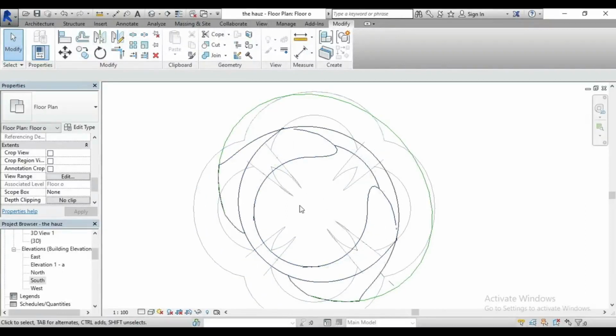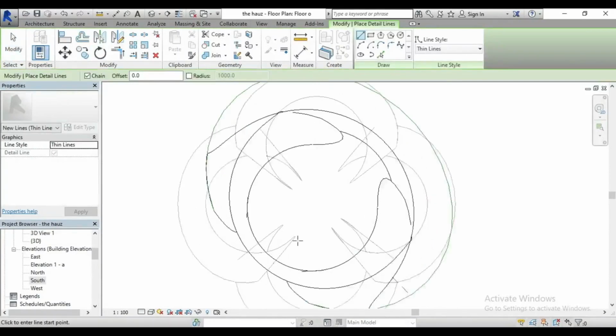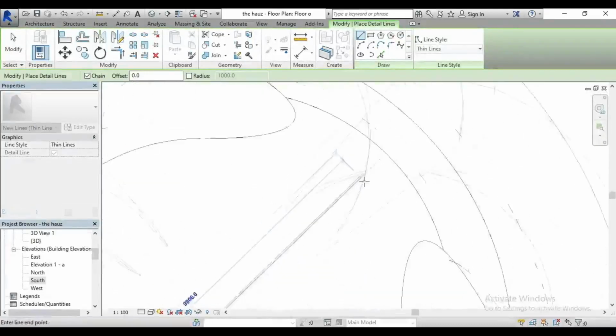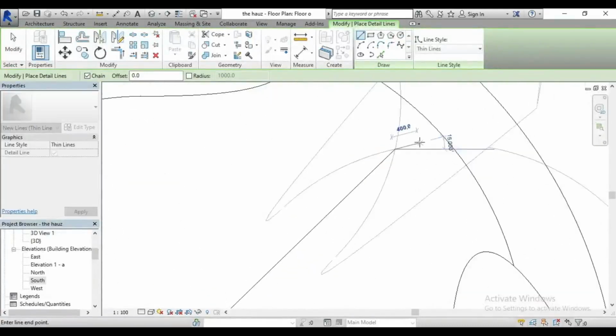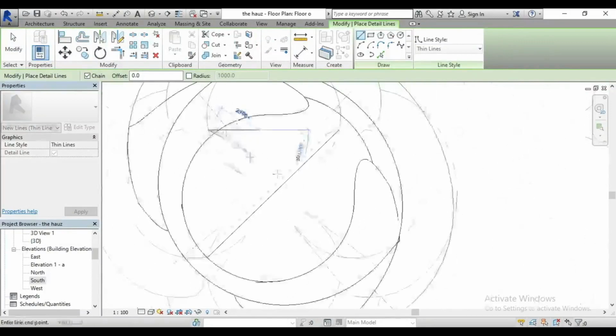And so when I'm working on that plane and following the lines, it will automatically be on that point, and not intersecting or shooting out from the object, since I'm working with a curvilinear model. So I'll draw a line like that, a guide. These are guidelines, remember, detail line, DL, enter.